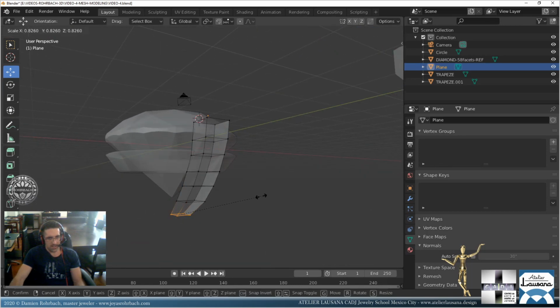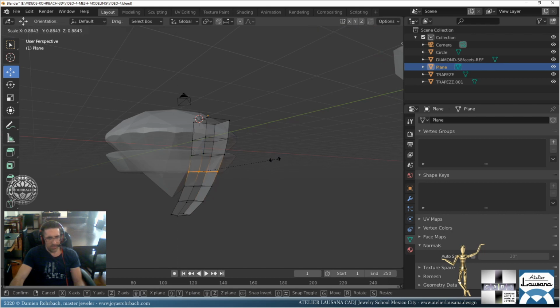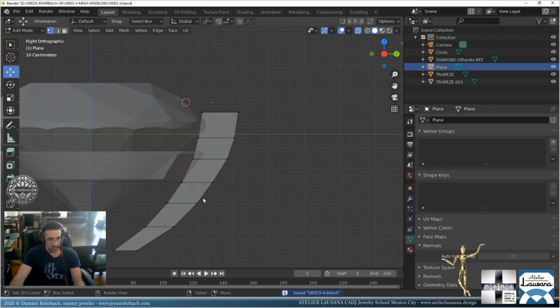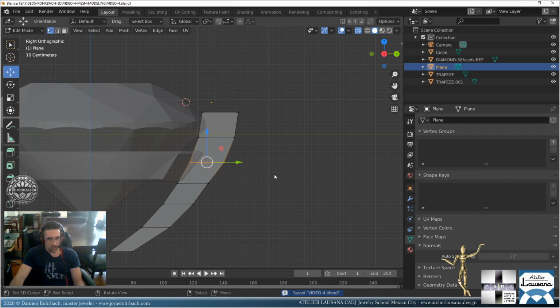I'm going to make this smaller, and not smaller than 0.5, right? You can do it, but you might face some problems, especially if you're a beginner and you want to manufacture the jewel. It's doable at a smaller size than 0.5, especially with the new printers and casting machines, but it's still not recommended because of the quality. Of the jewels we want quality, don't we?